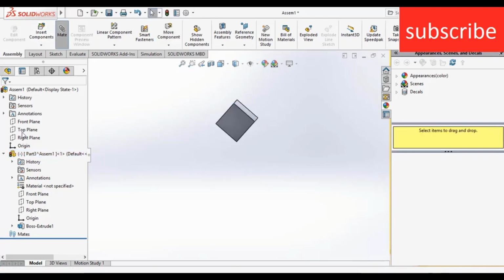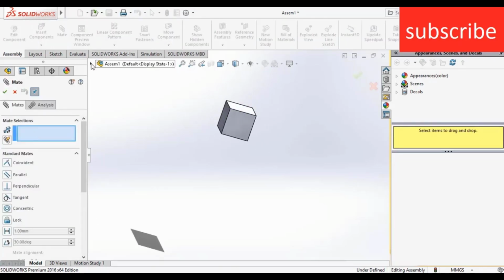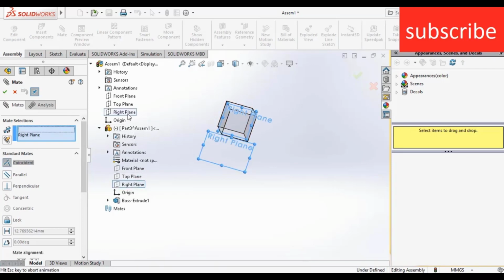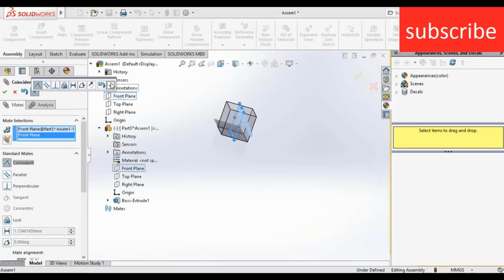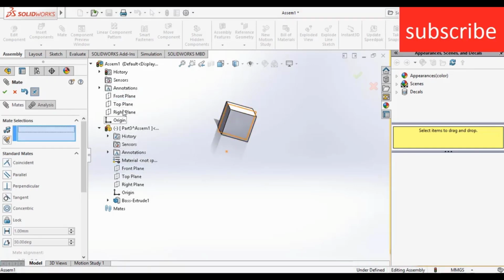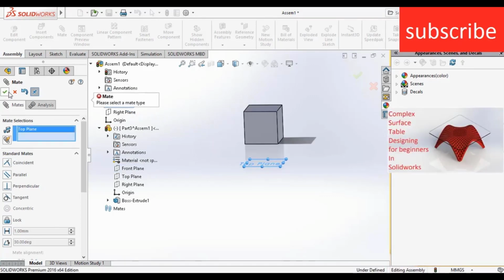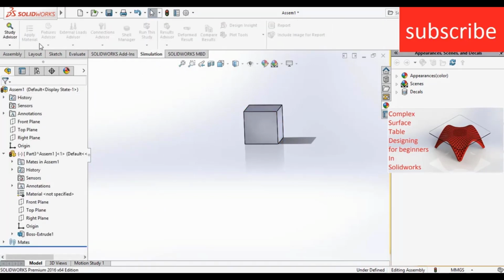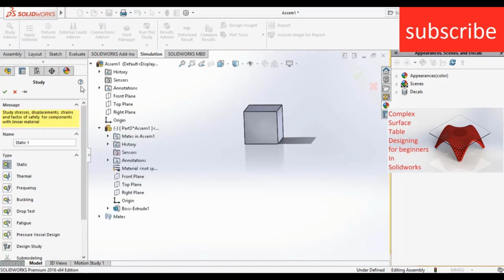Now go to mates, select right plane and right plane of the assembly, click OK, and select front plane and front plane of the assembly, click OK. Make sure it doesn't coincide with the top plane. Now click OK. After that go to simulation, go to new study, click on drop test.